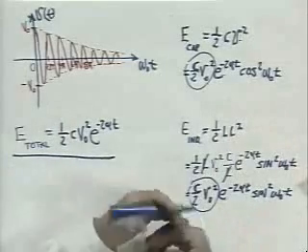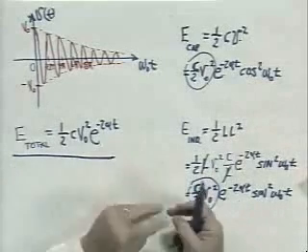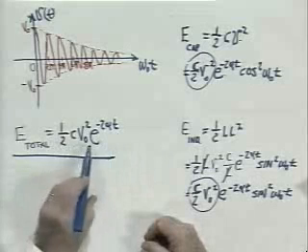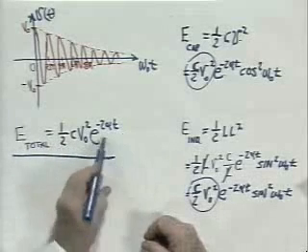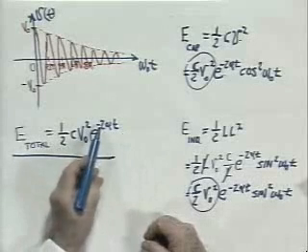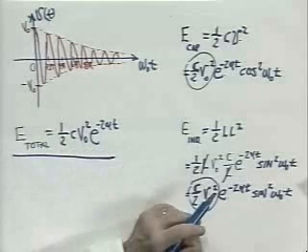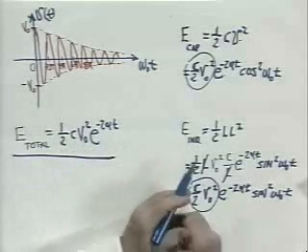So the total energy stored at any instant of time, shared between the inductor and the capacitor, is a constant. As time goes on, the energy decays exponentially with a time constant 1/2 alpha towards 0. But at any instant of time, the total stored energy is constant.